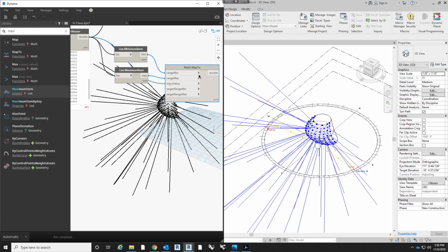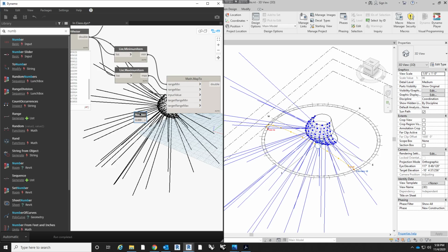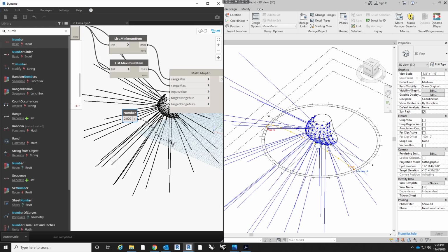And then it's asking for a target minimum and maximum. So our target minimum and maximum are from our NCP, and we want that to be either 0 to 5 or 5 to 1. And so we can specify that by using a number. Actually, let's use 0.51, because remember, if it's exactly 0.5, it's going to error out because all the points converge on the same place, and it won't create that surface. And then our final number will be 1. That'll be our maxed out panel.